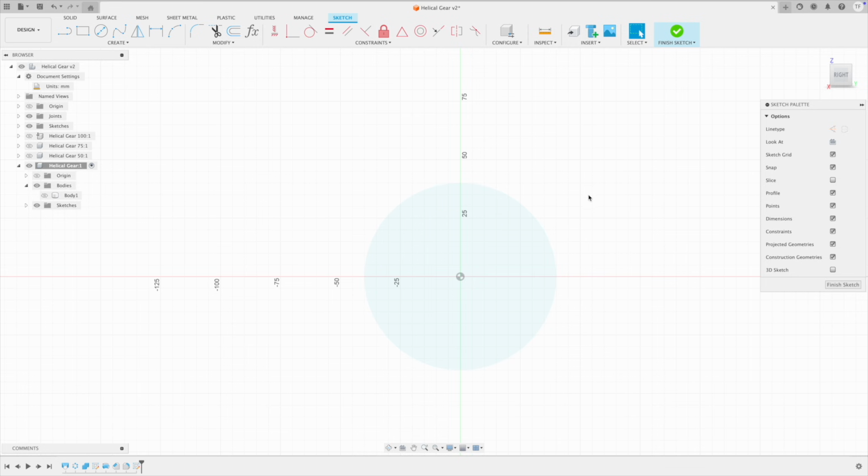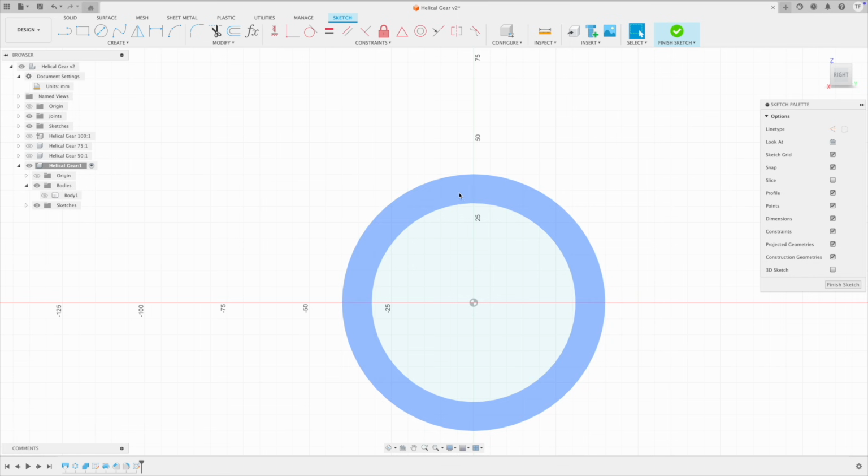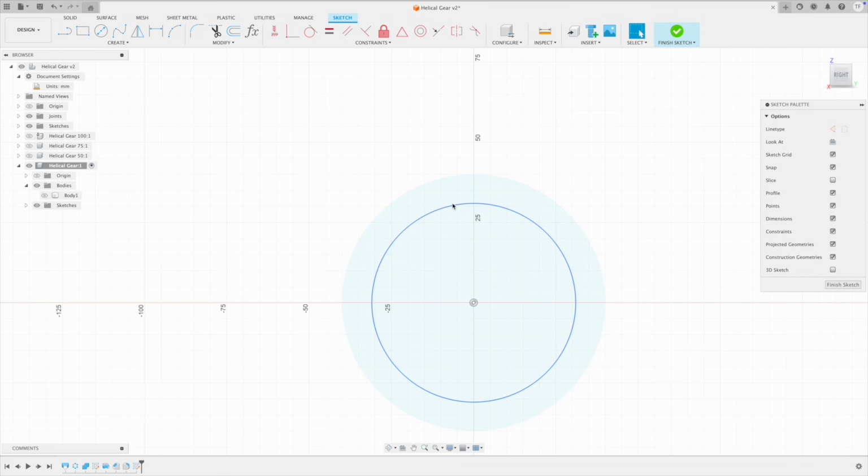This is one other reason why we usually don't create a fillet before we finish our sketch: if in the future we delete the fillet, then sometimes this sketch, even though we've created the sketch on this profile, there might be some warnings. So generally we save fillets and chamfers to the very end. But in this case, let's create our dimensions, and we can actually pick, remember, because I created a sketch on that face, it's inherited these dimensions. It's kind of hard to see, but that's all right. Train your eyes to see it.